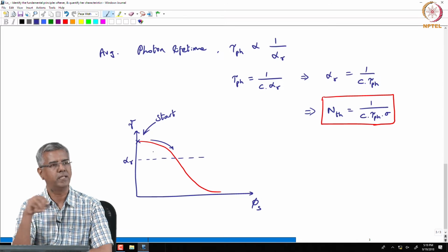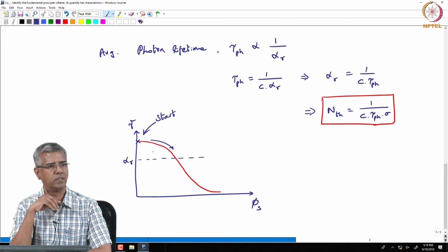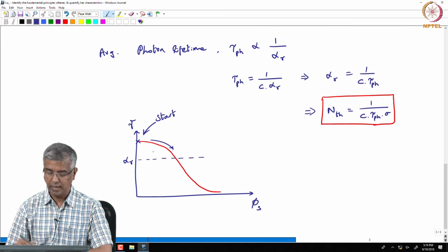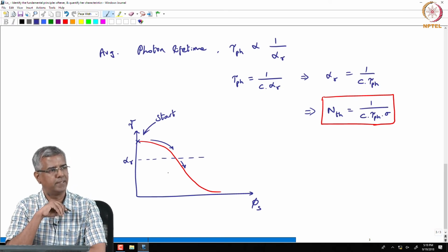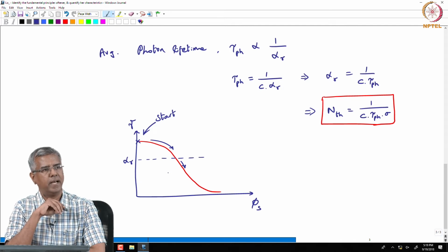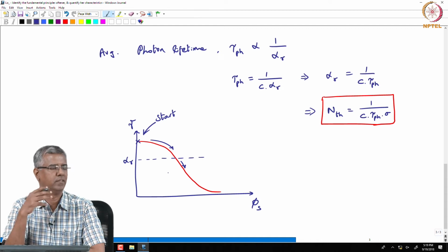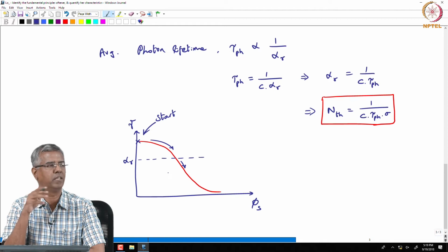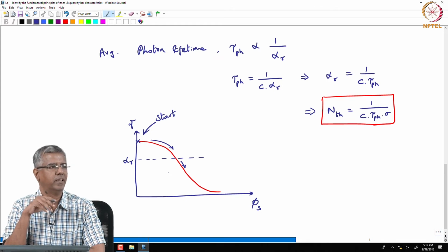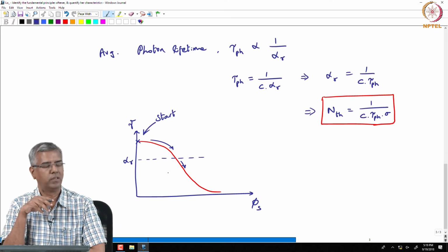but as you build up the photons inside the cavity, you are going to saturate the gain medium, right. So, the gain is actually going to decrease as you build up the photons inside the cavity, and it may decrease to a point even below alpha r, right, at which point your stimulated emission is not as much. So you basically have spontaneously emitted photons, and those photons are going to be very few, right?